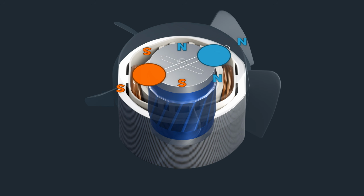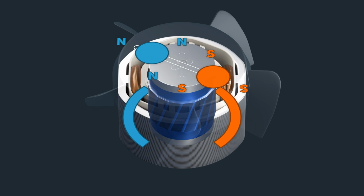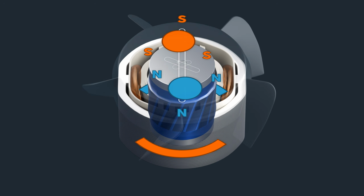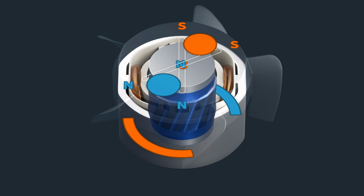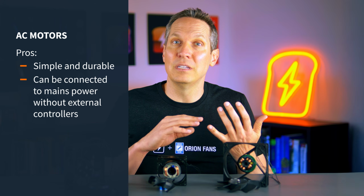This changing magnetic field induces a current in the rotor, which then creates its own magnetic field. The interaction between the stator's and the rotor's magnetic fields produces torque and causes the rotor to spin. Basically, the rotor is following the rotating magnetic field of the stator, but never quite catches up. As I mentioned, AC fans are simple and durable, making them a rugged solution. They can also be connected directly to mains power without the need for rectifiers or external controllers.